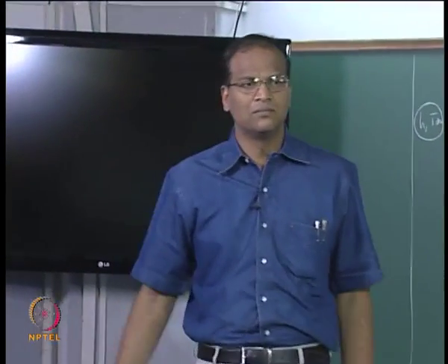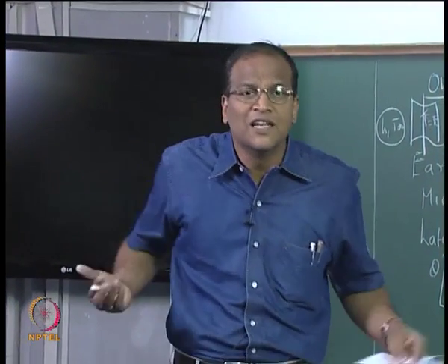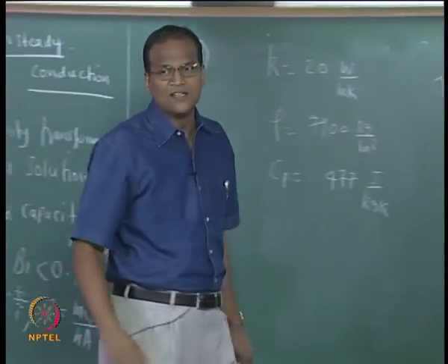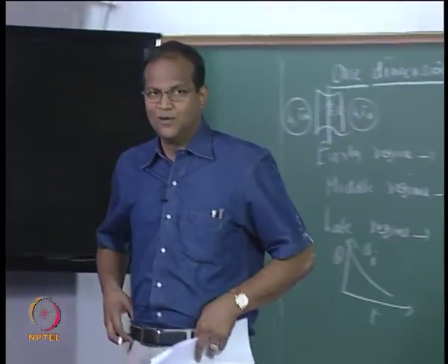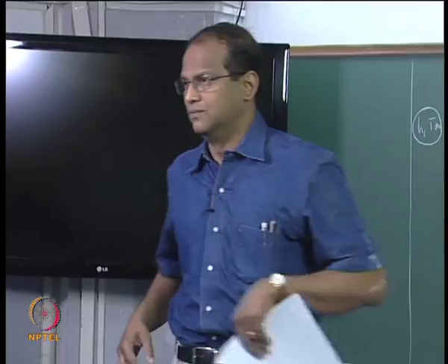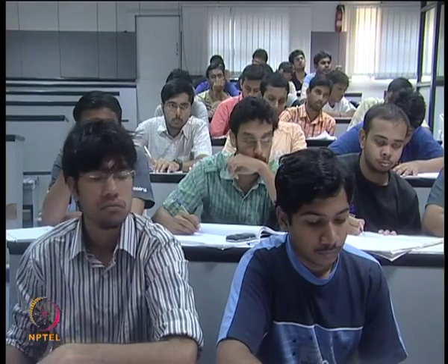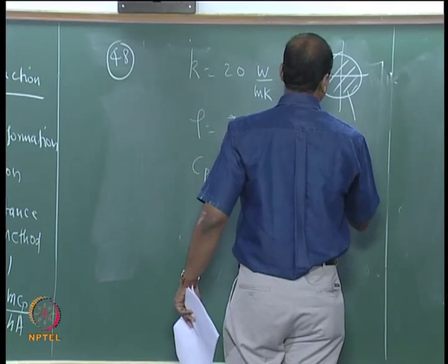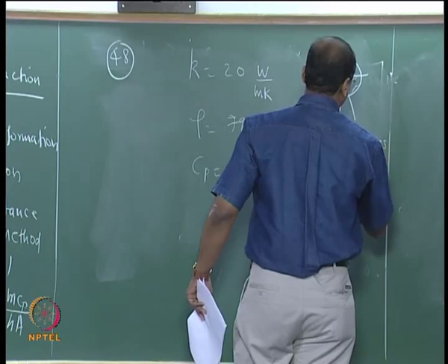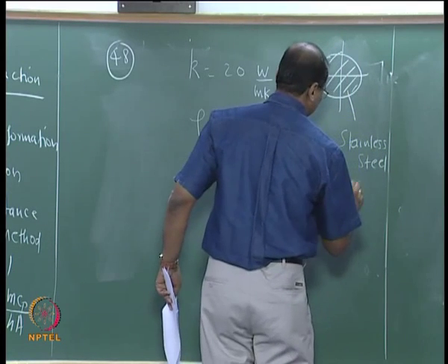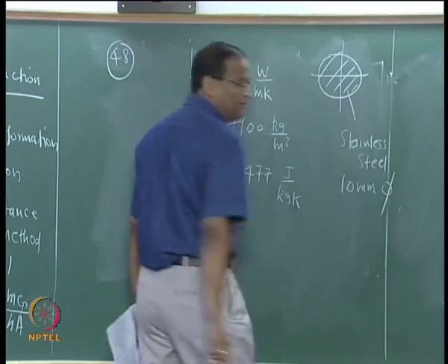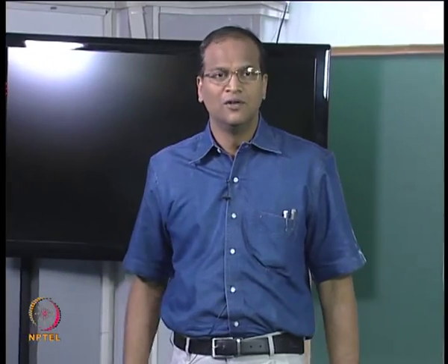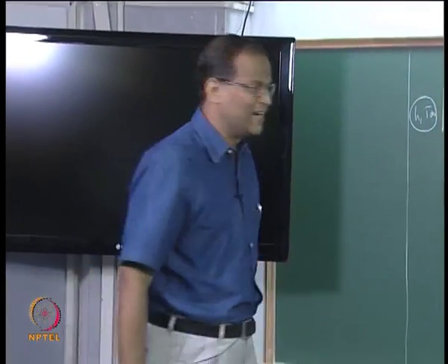What is the question? What is the time required for the cooling? This is a question which can be answered only by the heat transfer engineer. Ten millimeters in diameter. The first step in technology is Biot number. First check whether Biot number is all right.